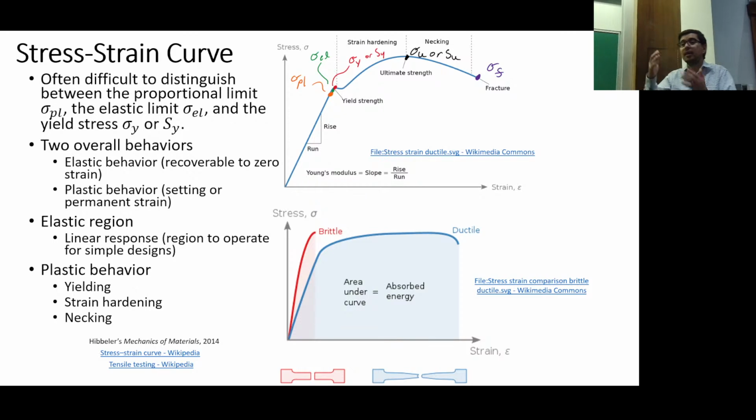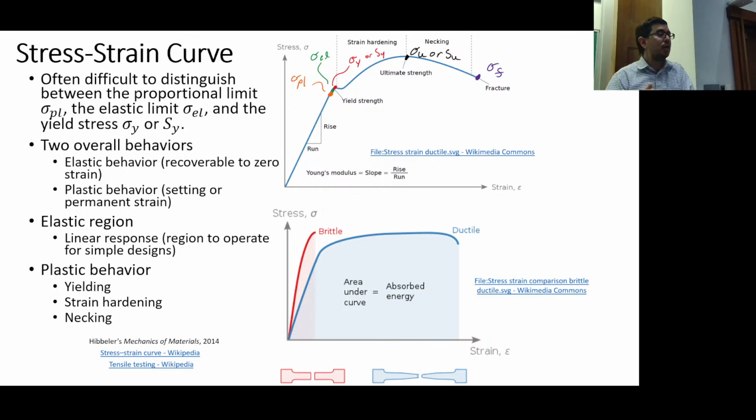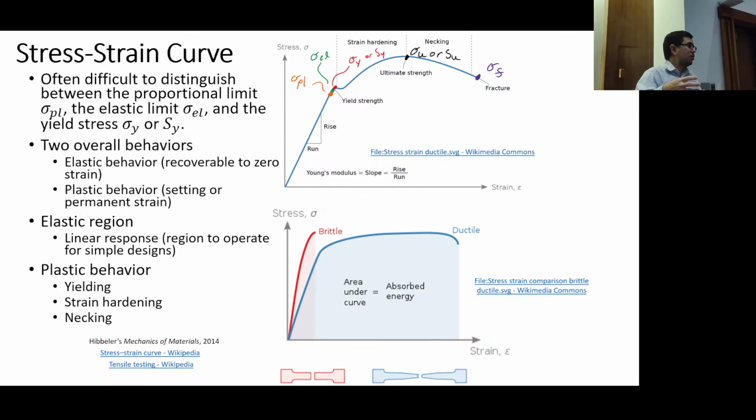We're mostly interested in what is the yield strength. Okay? We don't want to design for this area. Why? Well, you're going to have some elongation of your material. Okay? You're going to potentially have some variability that contributes to hitting fracture, which you don't want to do. And the material doesn't go back elastically.